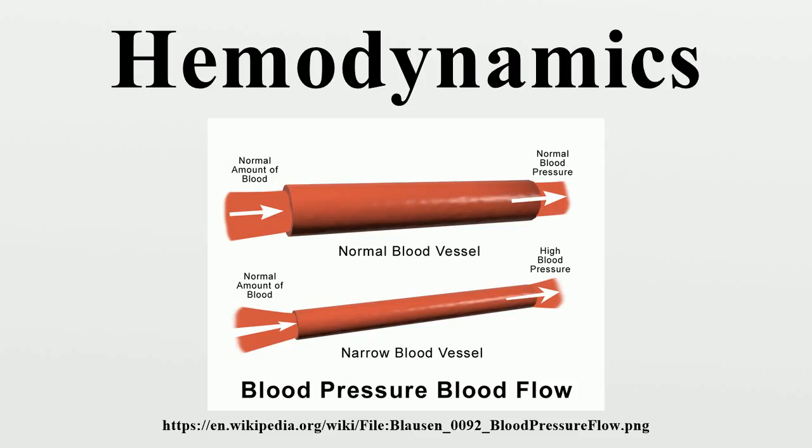Resistance is also related to vessel radius, vessel length, and blood viscosity, as indicated by the Hagen-Poiseuille equation. The equation is as follows: ΔP, the pressure drop or gradient, equals 8 μ L Q over π R to the fourth, where μ is viscosity and L is the length of the tube. In the case of vessels with infinitely long lengths, L is replaced with the diameter of the vessel, Q is the flow rate of the blood in the vessel, and R is the radius of the vessel. Assuming steady, laminar flow in the vessel, the blood vessel's behavior is similar to that of a pipe.